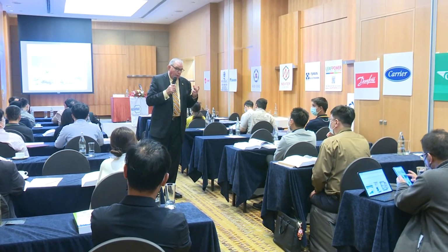So we, as test and balance professionals, have to hook our instrumentation up to it and read what we read and read what the device reads, and then calibrate the device that way. Most of the time, we're very near to the factory calibration, but still, we're required to be within 10%. So if it's outside of that 10%, we have to calibrate it down to make sure it's okay. So we're supposed to do that on all water and air flow meters.